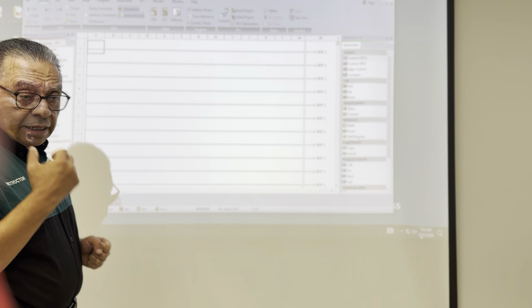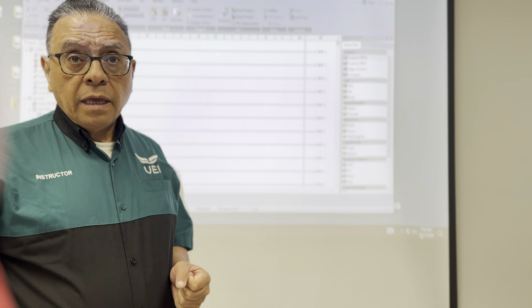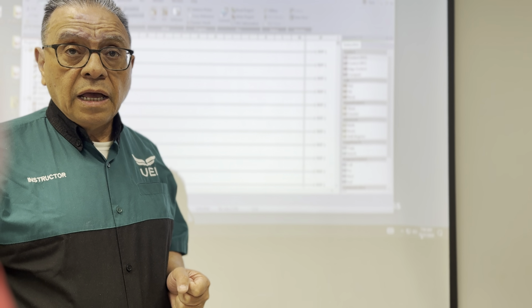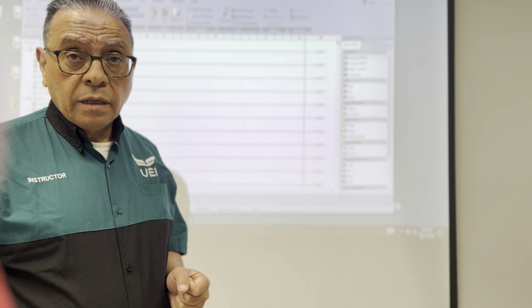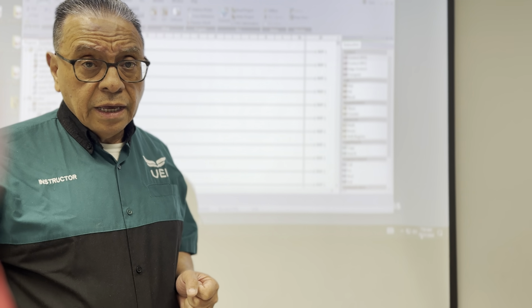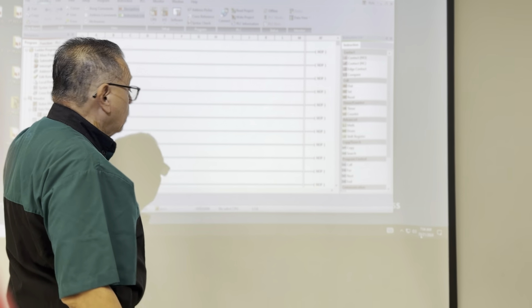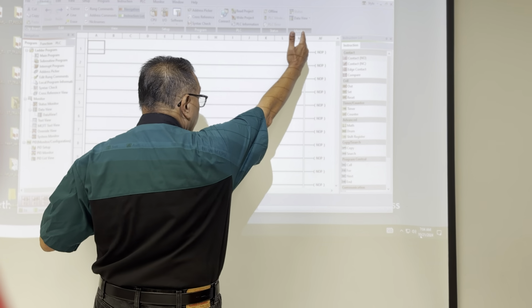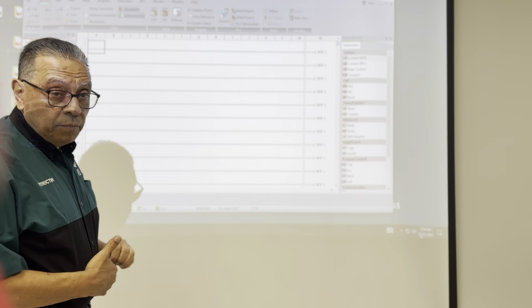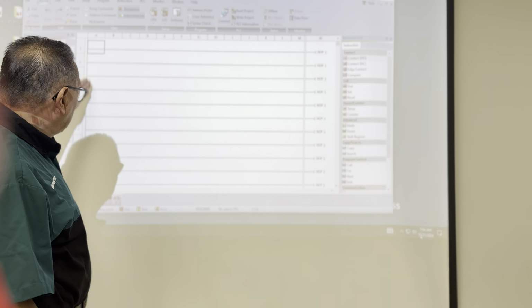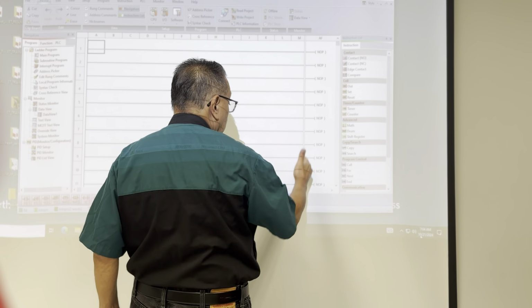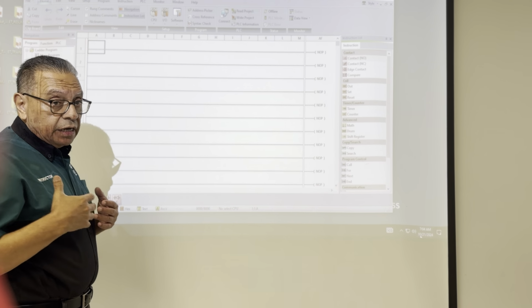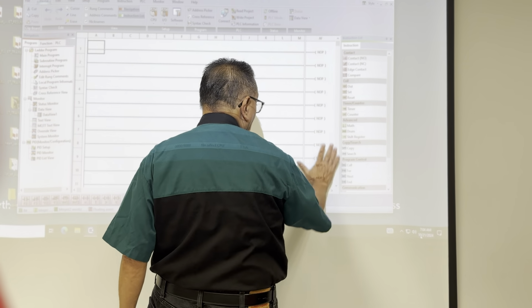I will use this example because normally the electrical automatic control system works at low voltage level, maximum 120. However, it could be a system that uses 208, phase 1 over here, phase 2 over here. But I will be using the low voltage system that includes L1 on the left side and the neutral on the other side. And as I told you, this is the conditional area in which I will create my conditions, and this is the output area.